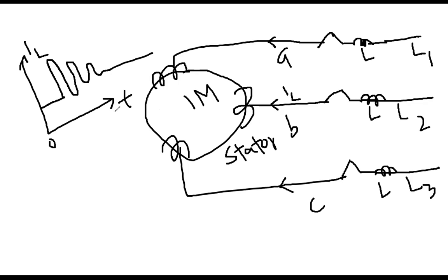So how will it mitigate the transient? You all know the function of the L. It impedes the rate of change of current. Current through the coil cannot change immediately. So there can be some transient, but very small. It will go ahead, then immediately it will be mitigated. So then these coils are safe.